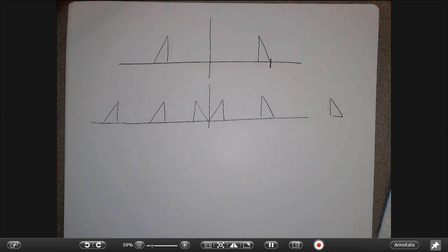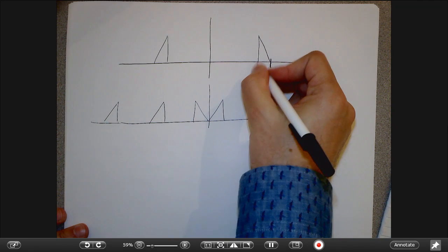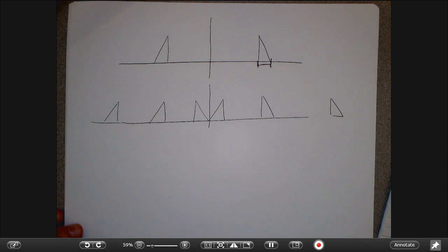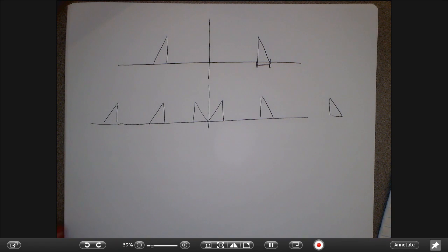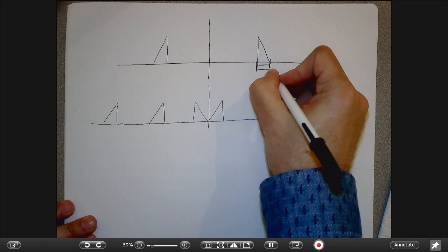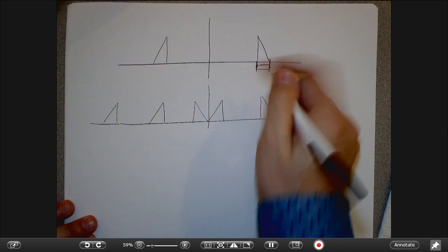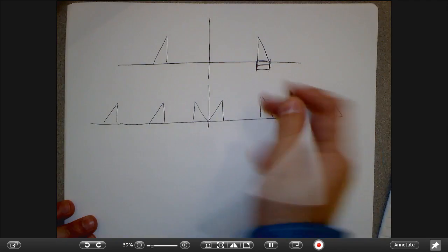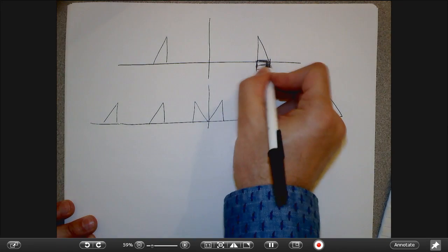So that's a fun little problem to figure out. If you knew that the thing I cared about was in some very narrow frequency band, then the intuition is that the sampling rate you should be able to achieve should be related to the non-zero bandwidth of the signal, not this whole distance, but only the part that's occupied.